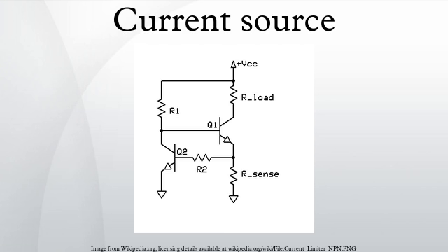The circuit to the left overcomes the thermal problem. To see how the circuit works, assume the voltage has just been applied at V+. Current runs through R1 to the base of Q1, turning it on and causing current to begin to flow through the load into the collector of Q1. This same load current then flows out of Q1's emitter and consequently through R sense to ground. When this current through R sense is sufficient to cause a voltage drop that is equal to the VBE drop of Q2, Q2 begins to turn on.